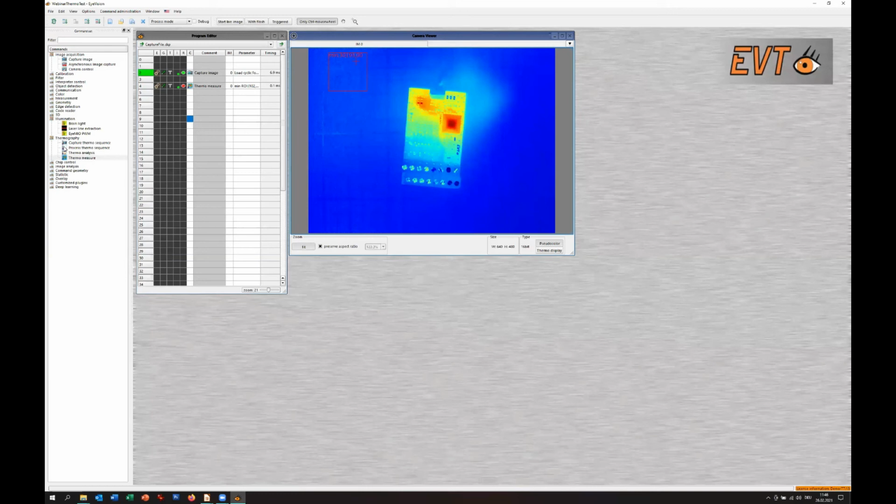So that was a short note I wanted to tell you, because sometimes someone tells us, oh, I have this camera and I see nothing. Your software is not working. Then he explains, okay, this is the material, this is what we want to see. And then we can tell him, yes, look to the active wavelengths and look to your camera, and in these wavelengths the camera sees nothing. And then, of course, whatever software you have, it doesn't see anything.